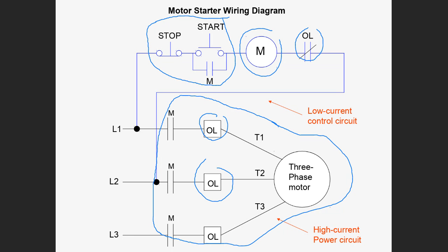So a motor starter is just a contactor. And remember, a contactor is just a heavy-duty relay. So basically, this is a heavy-duty relay with another relay wired in with circuit protection to protect against overloading the circuitry. And notice again the three-phase here. So we have three sine waves we're feeding this, but that's a different topic.